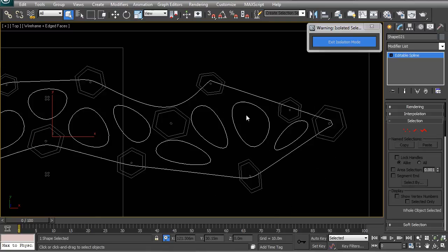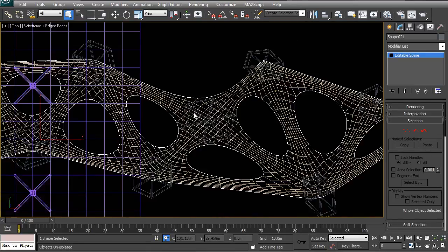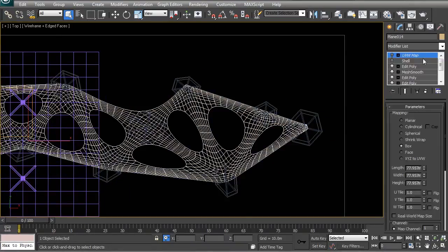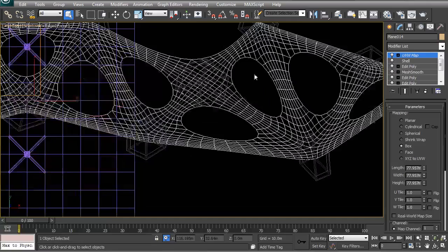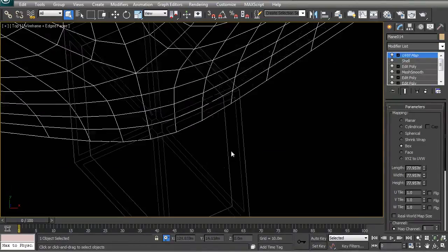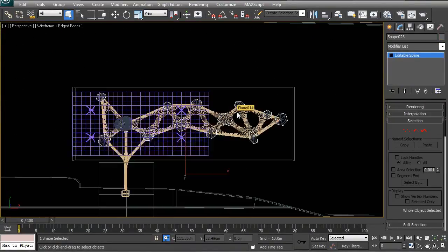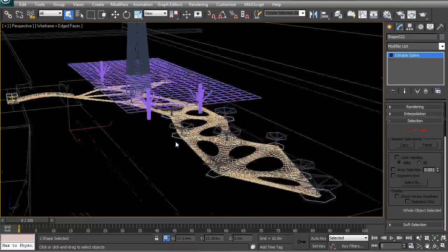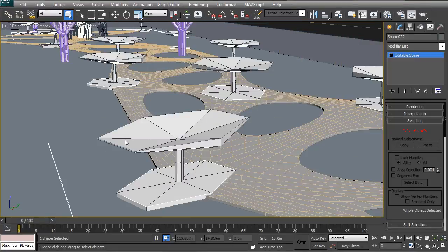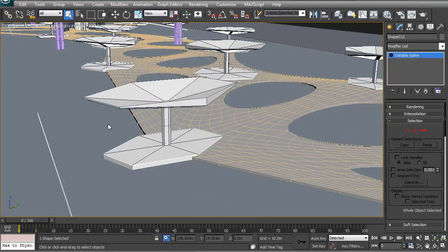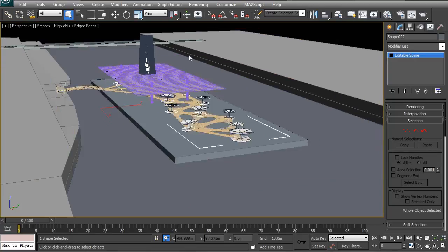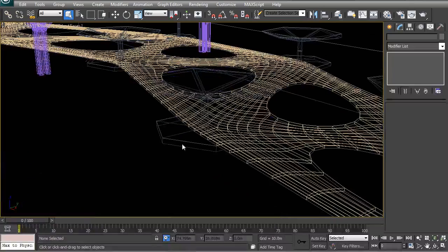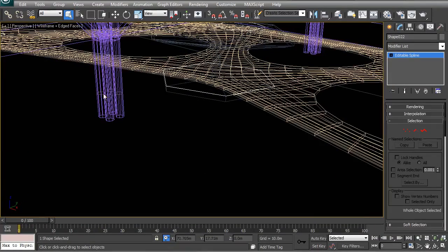Also, one thing I would like to have a look at here is you can also go backwards and forwards to just see that everything is in its correct place. For example, you would want to just make sure that all of the edges are there. Make sure that you know which of the edges is at the top and the bottom. In other words, is the canopy bigger than the base, or is the base bigger than the canopy? The last thing you want to do is make a mess of that and basically draw this as being the ground floor and this as being the canopy. So just get to know your building, and then you'll be able to handle the process quite easily in AutoCAD once you pull that information across.